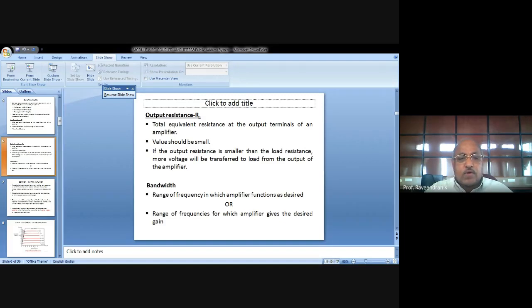So in that way, you can find out IC, and it is clear from the above expression that IC does not at all depend on beta. Here there is no beta term. IC is equal to V2, that is voltage across resistance R2, that is VB plus IERE, isn't it? V2 minus VBE divided by RE, that is the resistance at the emitter lead, and the resistance comes at the emitter lead, isn't it? So IC depends only